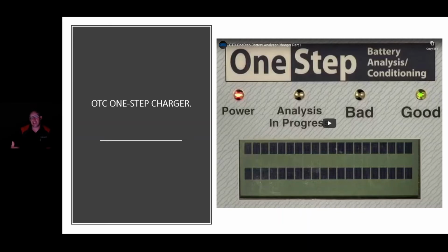The tester does a battery analyzing, a conductance test, and then it brings the battery to a charged state that would be good to be able to test the battery again and finds out whether or not it can actually hold the load like it's supposed to. And then it does a load test on it too. So this is a very accurate tester. It's called the Midtronics tester.